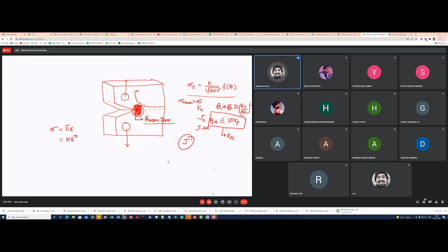But then at the crack tip, you will also be having void formation at some point, right? So you have damage there, and this discontinuous damage is not included in the theory of plasticity. So that cannot be taken care of by the J integral, right? Which means that there is an area or a volume where the existing stress versus strain relationship doesn't work. Just hold on a second.